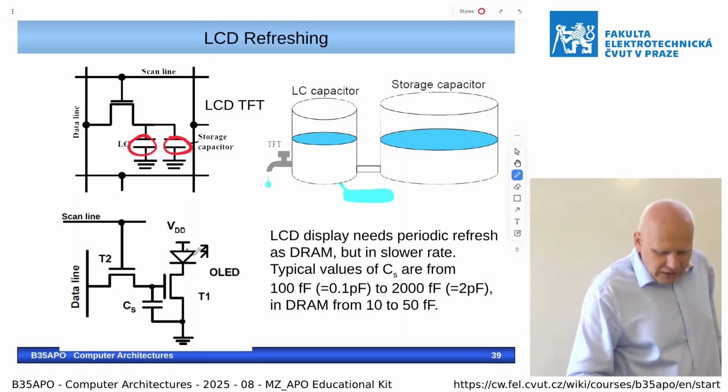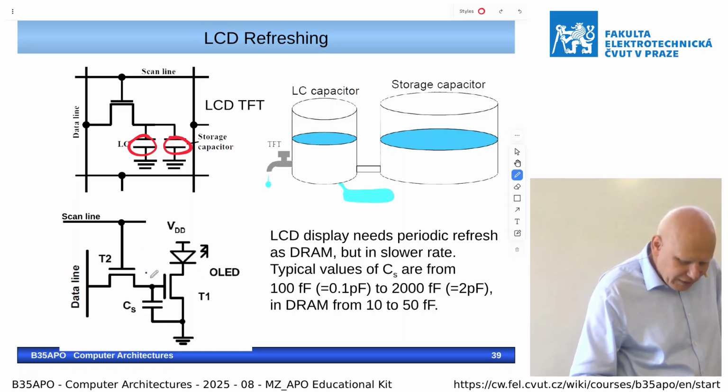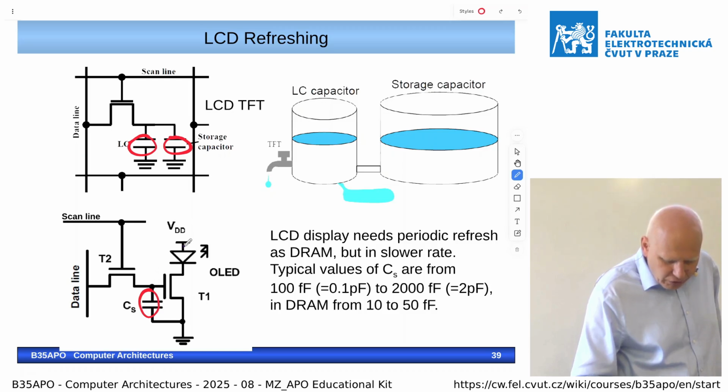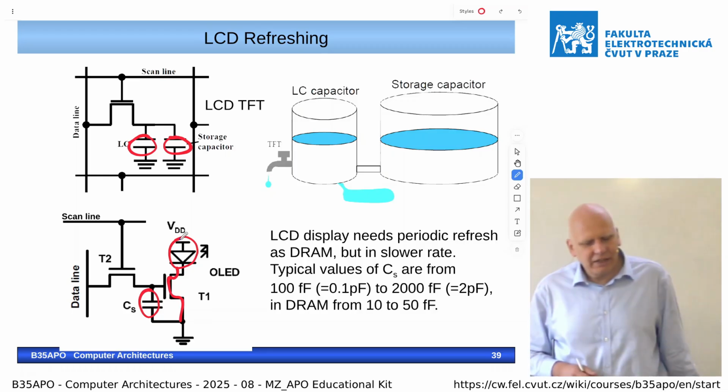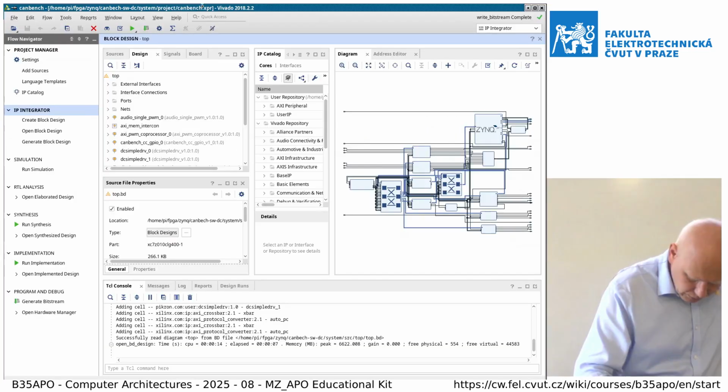In the case of OLED, organic LED display, it works in a relatively similar way, but we have capacitors which control only the resistance of some transistor which directly controls the intensity of the given LED.